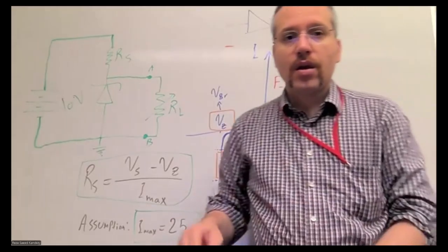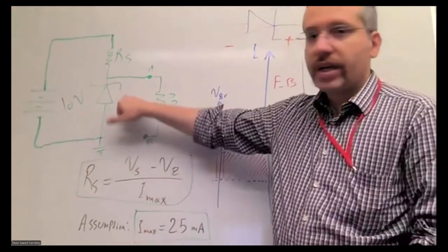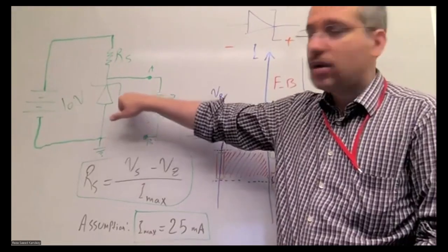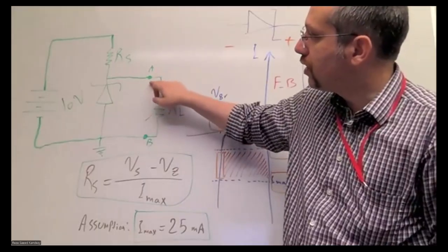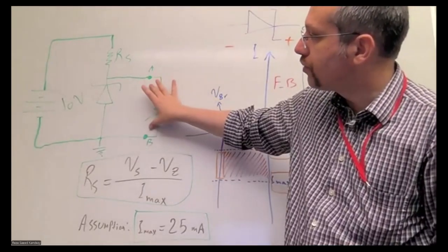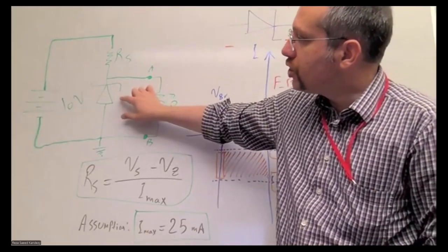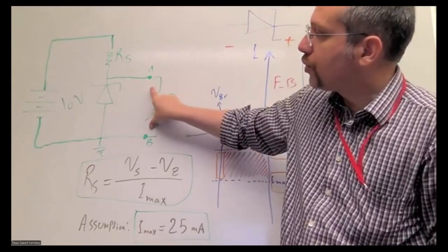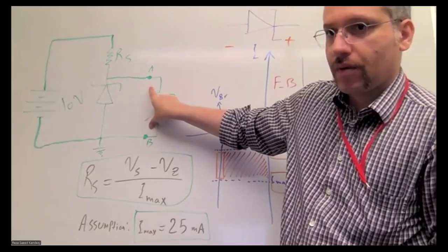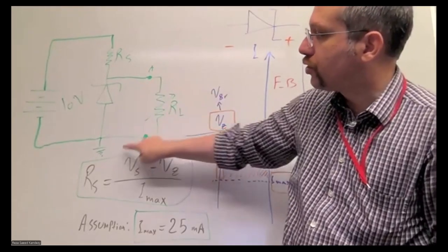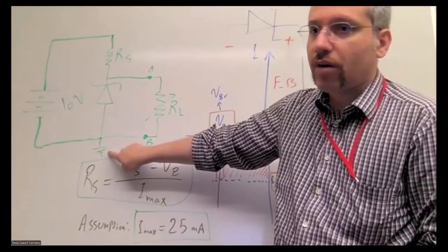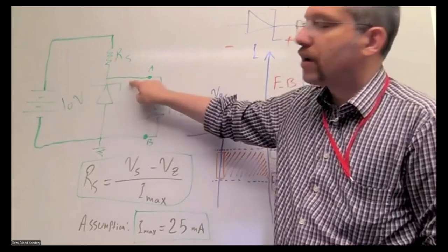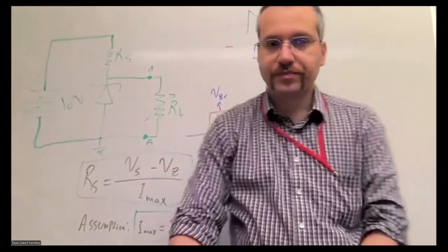Now, we place the Zener diode in a reverse bias across our output. So the terminals A and B are our output. So this should be in a reverse bias, parallel to the output, across the output. So this is the higher potential, this is the lower potential. As you see, I connected the ground to the anode, and the voltage will be at the cathode. So this is reverse biased.